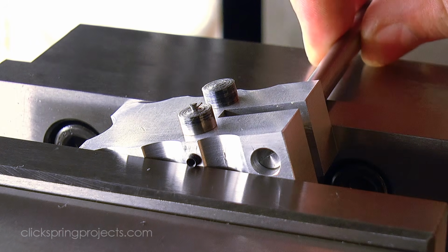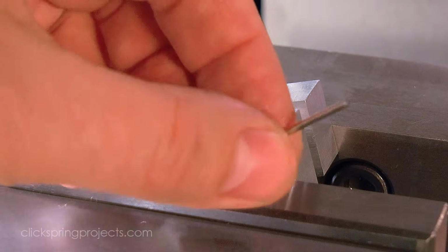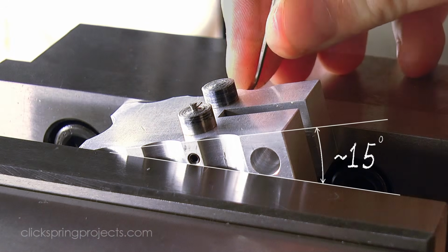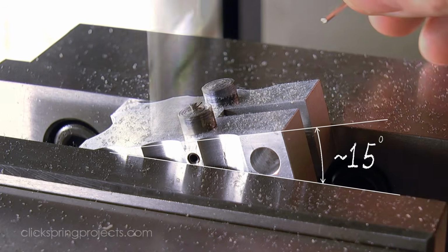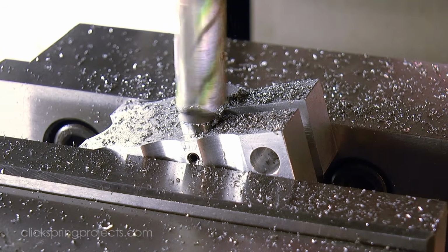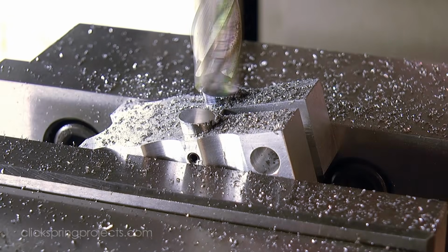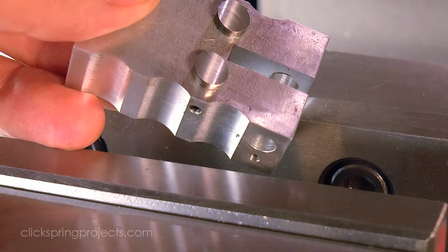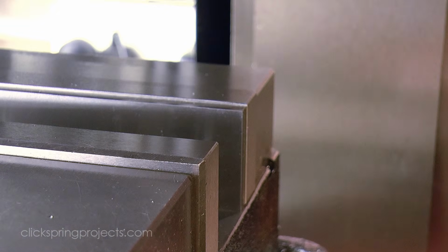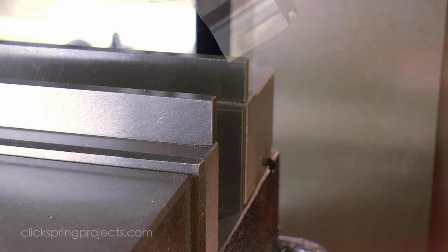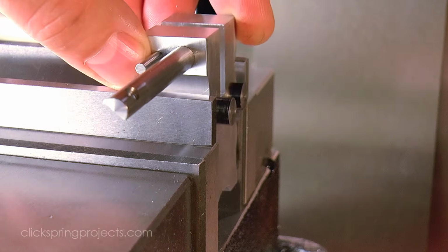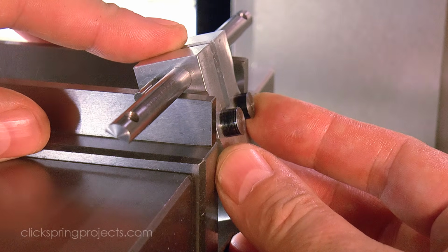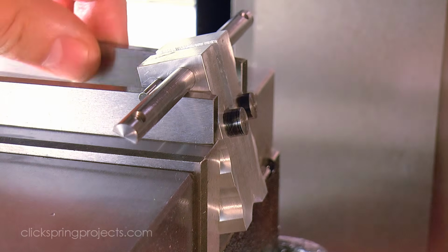Once the fixture is being held by the vise jaws, the grub screws can be tightened down on the button cutters. Now of course, it's not overly precise, but it doesn't need to be. It makes setting the angle convenient. And it'll certainly give us an angle close enough to the 15 degrees that we'd like to see. That's one way to set up the work, and here's an alternative. Again, the guide shaft and this time the indexing pin form a good approximation of a 15-degree angle.